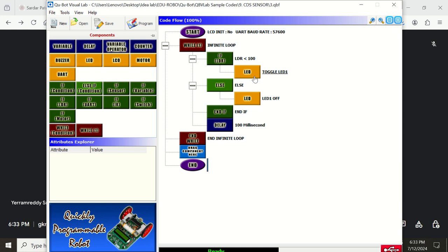on and off. So these all have sensors, analog sensors, and they are reading the physical variable continuously and it is converted into an electrical signal. Then the electrical signal is converted to a number, an analog number, means a binary number, which ranges anywhere from 0 to so and so number, let's say 255 in case of 8-bit. Then you can write a conditional statement, compare, take some decision, and that decision could be your choice: LED, motor, or some other actuators. Okay, so that's about example number 3.